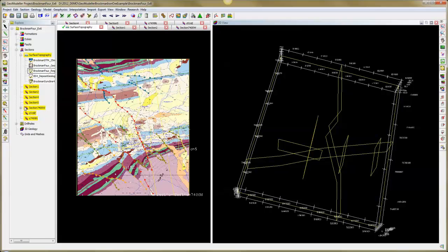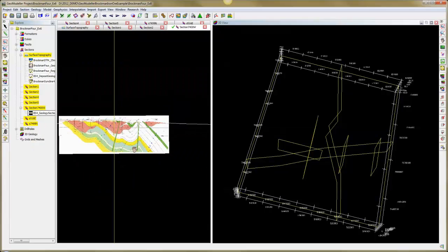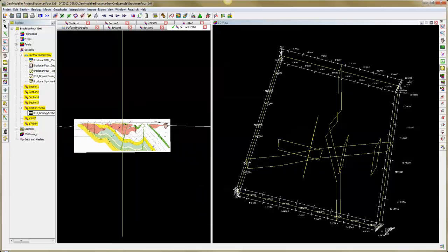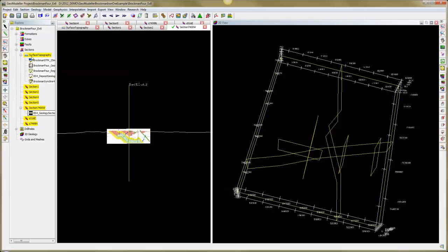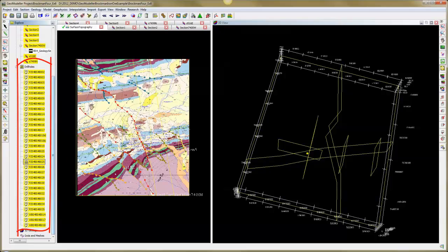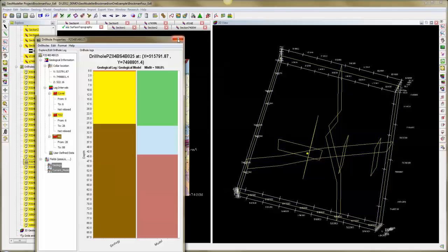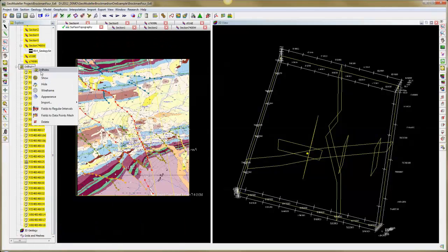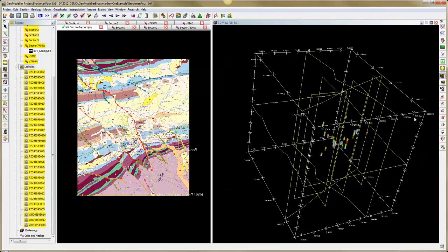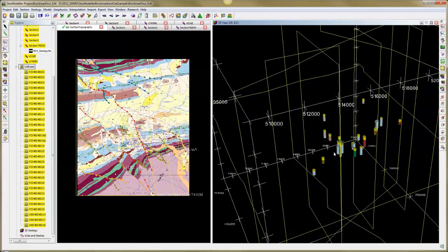You can see that in one of the cross-sections we also brought an image of a cross-section that helped us to put some contact data and build a geological model. We have also a lot more drill holes with, if I edit one of them, more geological formations. If I show them in 3D with vertical exaggeration, this is a group of drill holes that has been used to create the geological model.